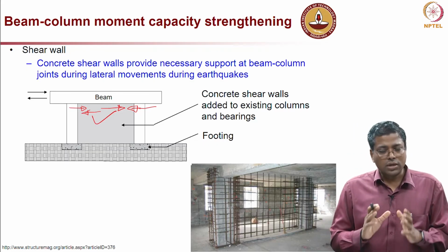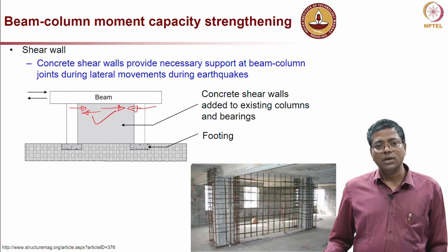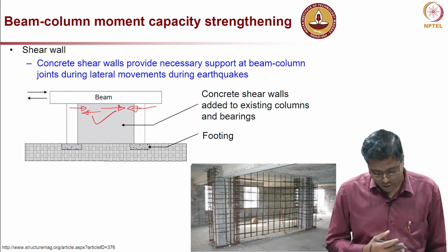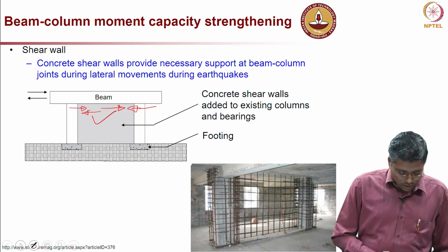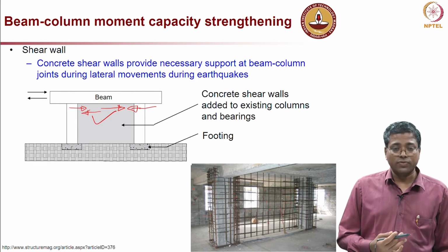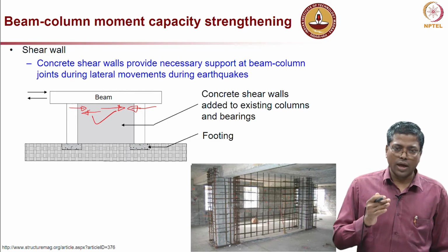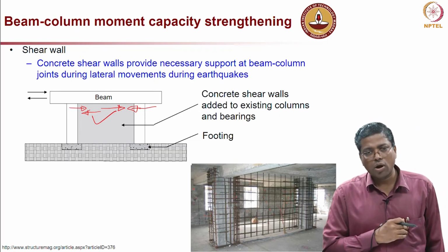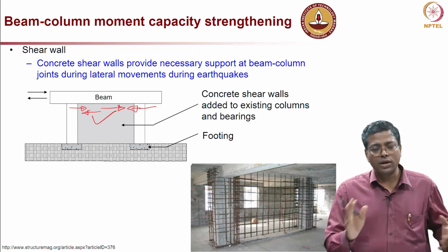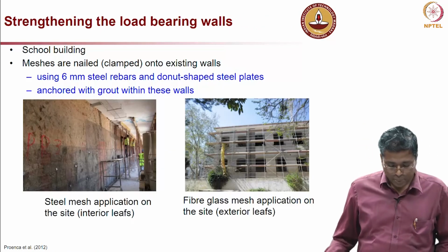So, it is a very good approach to enhance the earthquake resistance of many of our buildings, especially the parking lots. If you have a ground floor parking lot, think about this problem and see if some of the space between the concrete columns can be filled with walls, so that even if there is an earthquake, your structure can be safe and you can be safe.